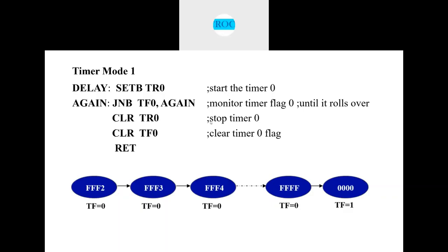The time required to execute this subroutine, from FF0 to FF. Once it comes back, for that long the P1.5 bit will be 0. Again it will be complemented to 1, and that value will stay for 1 till this delay.